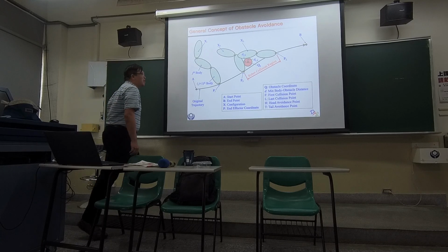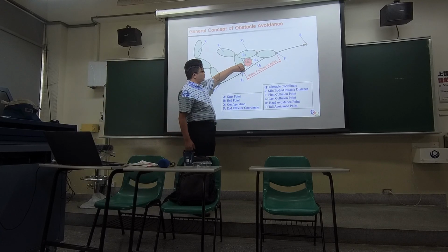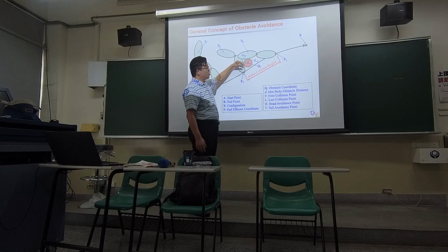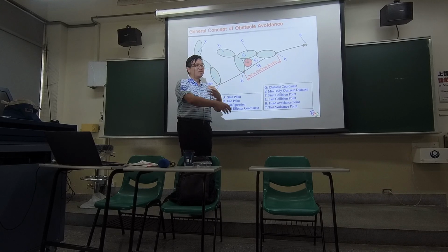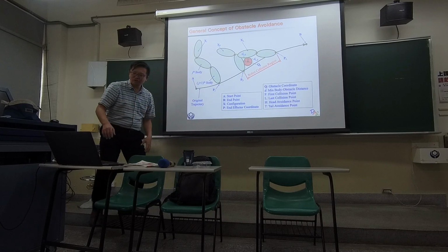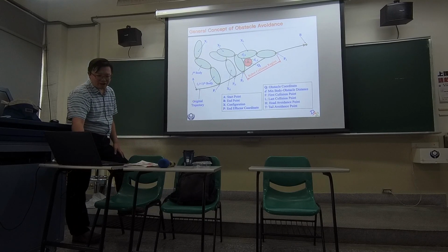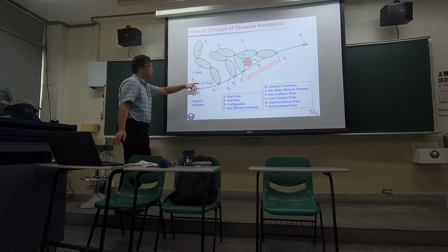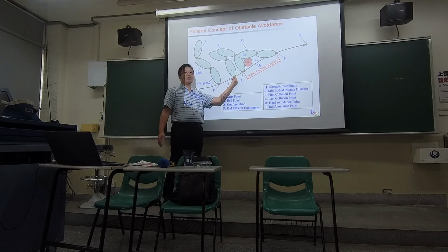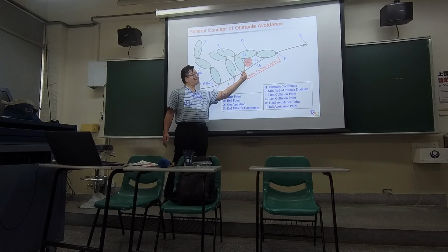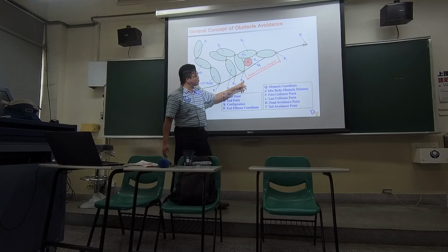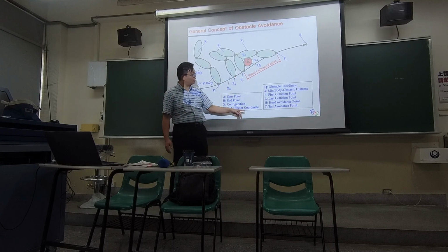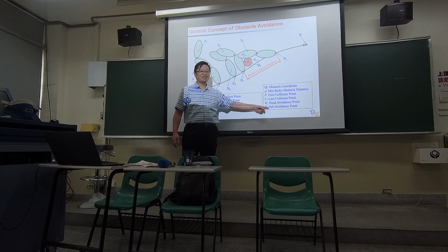However, if I move my robot up to here and start to make turns, you already have tangent contact. You don't want that. So in our research, we usually find a configuration a little bit earlier, away from the collision. Because we already use first and last, over here we use head and tail.